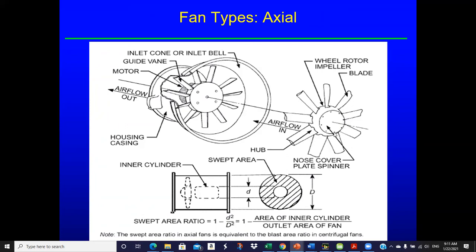I know some of the power plants on their really larger fans have gone to variable pitch blades. One reason is that those fans are so large, and if you're at medium voltage, the VFDs become more expensive, and they require cooling because of heat generation in the drive.